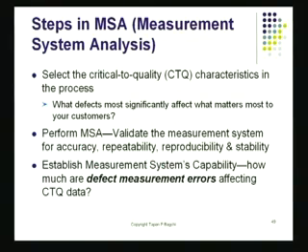unless you're able to do those things, if your measurement system, which takes the CTQ, makes a direct measurement and produces data, does a poor job, there is no hope at all that you'll be able to ultimately control the final process, because you'll be working with garbage. You'll be working with data that has a lot of measurement errors. So you've got to make sure you do this measurement system analysis. And one of the key things there is doing gauge R&R. This is something that you should be able to do.